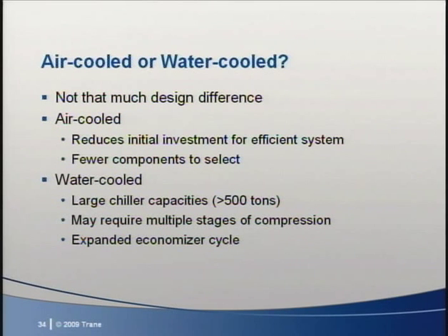Water-cooled chillers can be larger for economies of scale on larger projects. But from an ice storage design perspective, air-cooled and water-cooled systems are about the same. So all the elements we'll be describing today will also apply to water-cooled systems. There'll just be a little less selecting to do since we won't have a condenser pump and cooling tower.